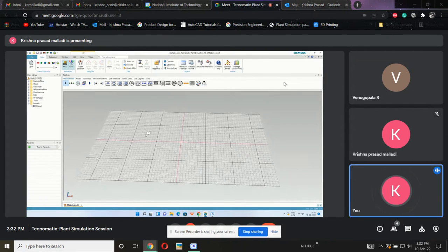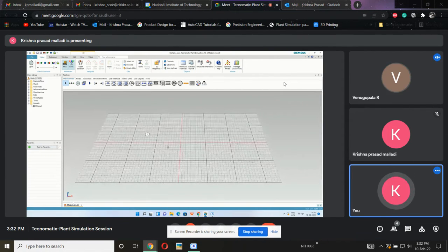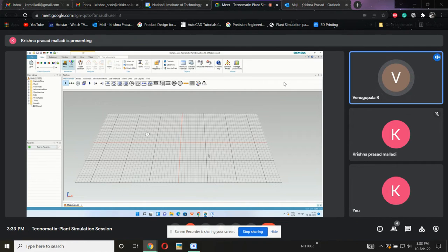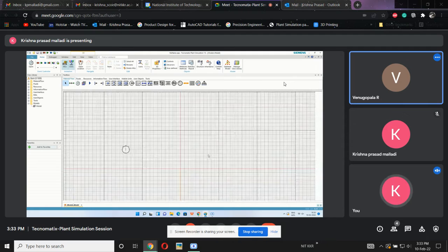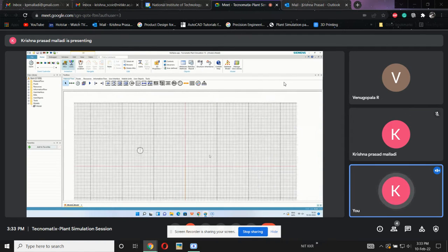I will show you. So this is actually the 3D representation. If I want to start a model here, it is difficult for me to place it exactly at my desired location. For that, we need to convert our 3D drawing into planar view, which means a 2D view, planes like the XY plane or YZ plane. We will be converting into the XY plane. For that, I need to press the letter P on the keyboard. Direct P. If I click this P, then automatically it will be in planar view in this XY view.